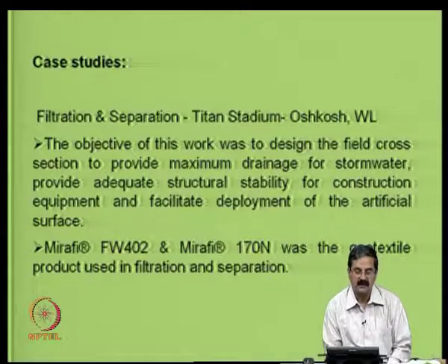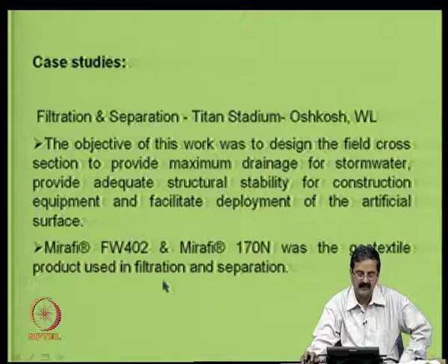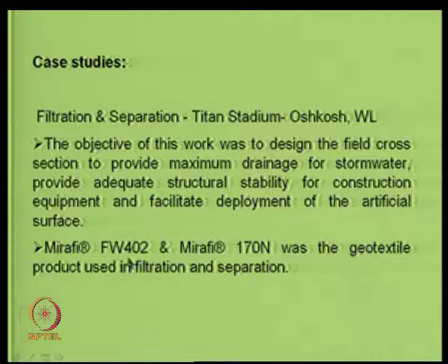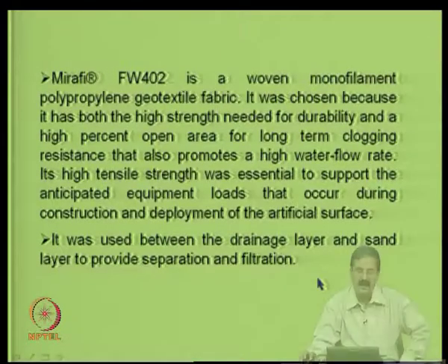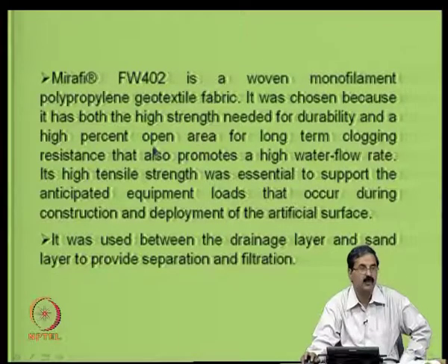In fact, a couple of things are there here. I must thank this company, Merafi, for giving this case study, and they have used some of the materials in this case. We will see that this particular component is a woven monofilament polypropylene geotextile fabric. It was chosen because it has the high strength required for durability and a high percent opening size for long term clogging resistance, and also permits high water flow, right.